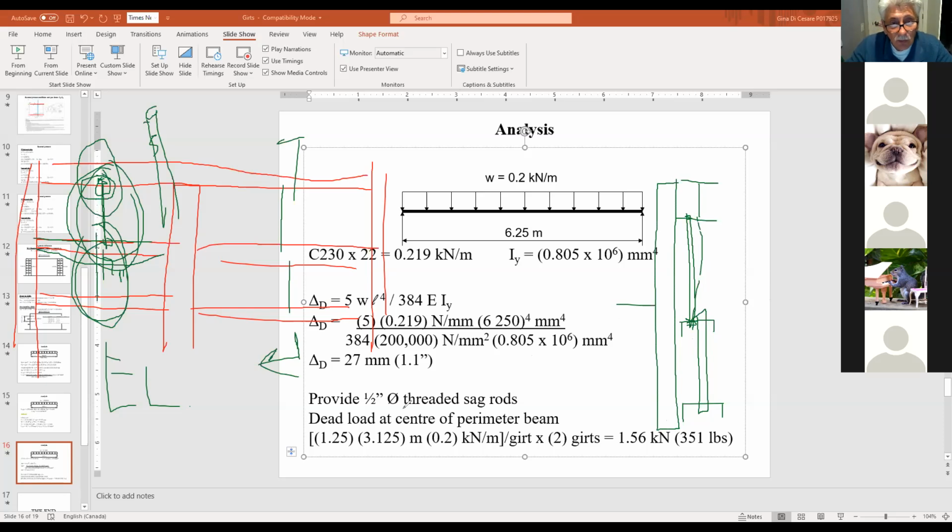What we're doing here is trying to determine, do you want to live with a 1-inch sag in your girts, or do you want them to be nice and straight so when they come and attach the wall panels to it, they'll stay nice and straight? Everybody likes to keep everything nice and straight, right? That's what these things do. They allow the things to stay straight so that when they attach the wall panels, once the wall panels get attached to the girts, these things become pretty redundant.